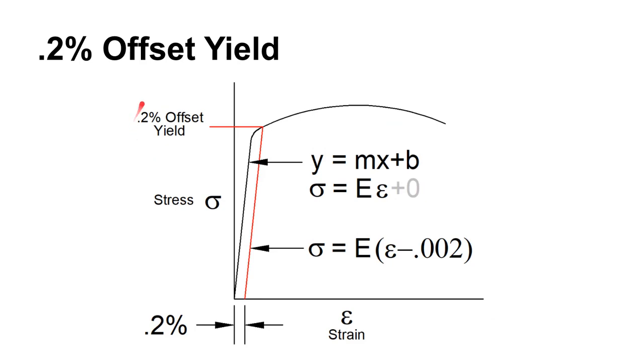All right, now the yield strength. Looking at this graph, and in fact looking at a real graph, it's even a little bit more ambiguous where the actual yield point is. But there's a nice sort of analytical trick that we can use here, and if we just standardize on this trick, then we can get really nice consistent yield point measurements and observations. All right, so this is how this works. First of all, we would measure the modulus of elasticity. That is, we would find the slope of this line.